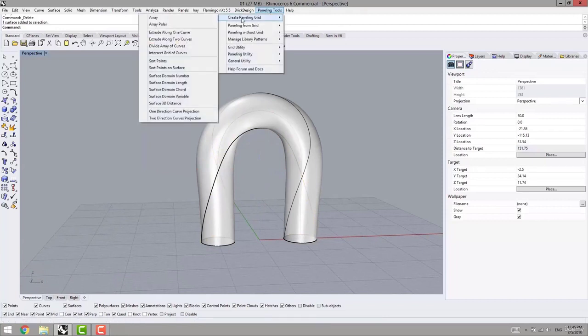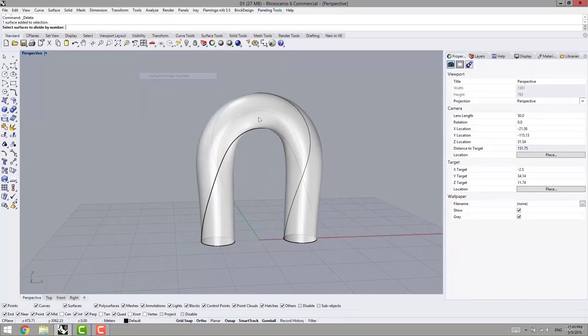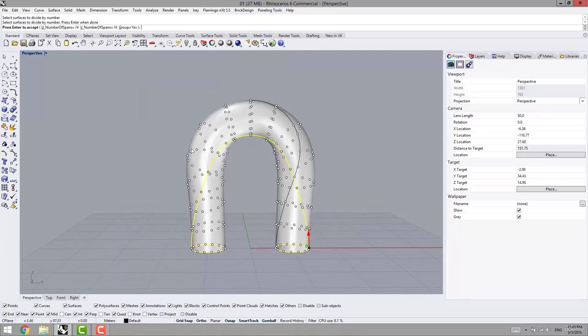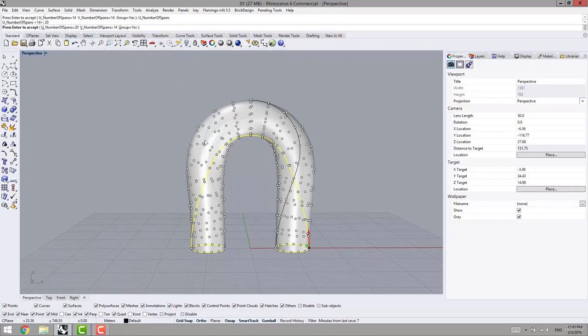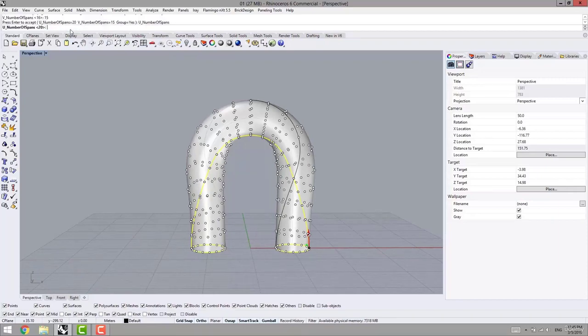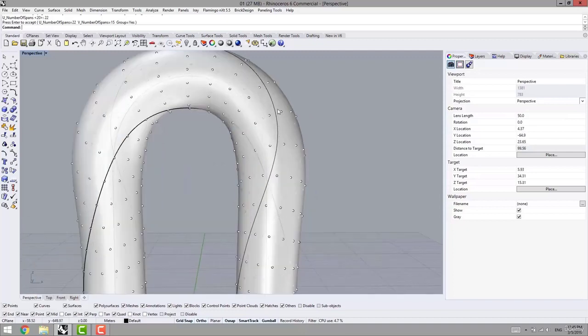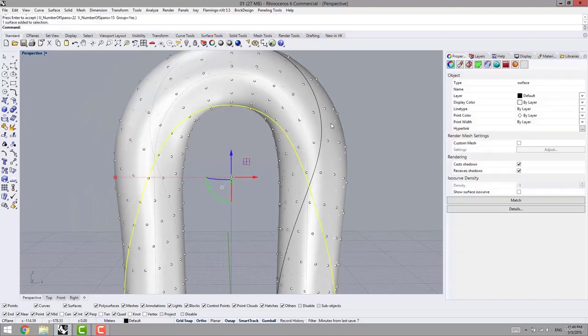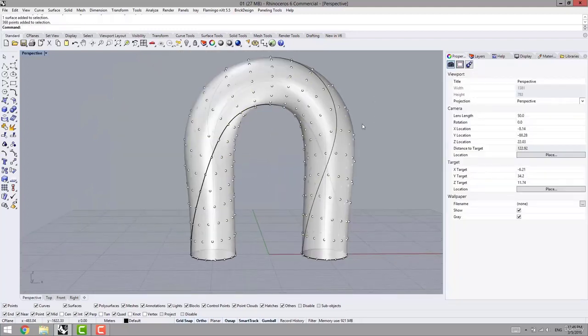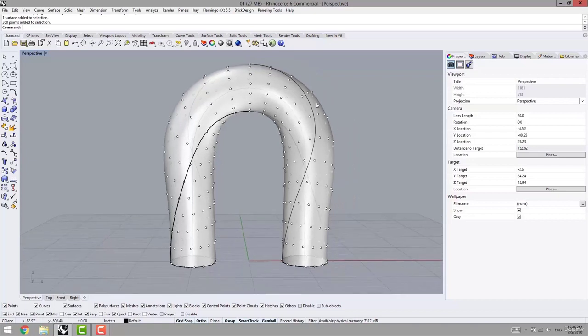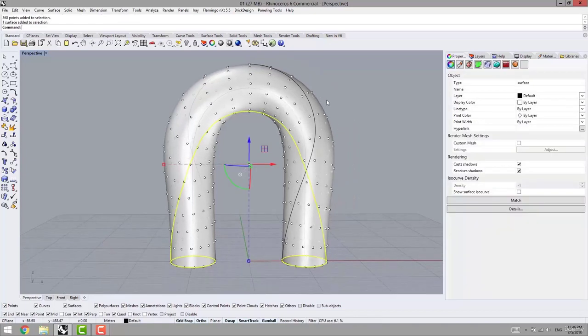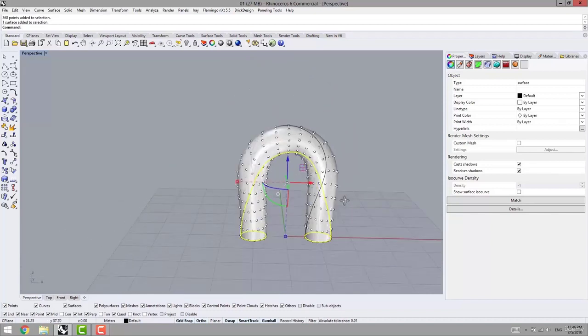After that, I activate the domain number to create a paneling grid for myself, like 20 by 60 or 15 by 22. The ways that we had for creating the second grid, we could make a copy out of that grid, but here in this surface we can't do that. The other way was to make an offset out of this surface. I applied the offset surface command